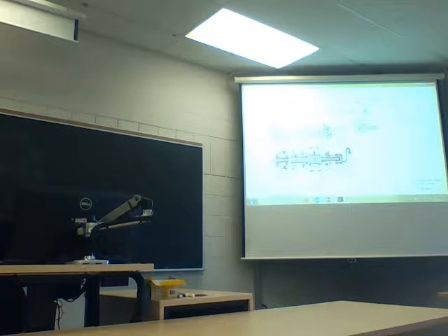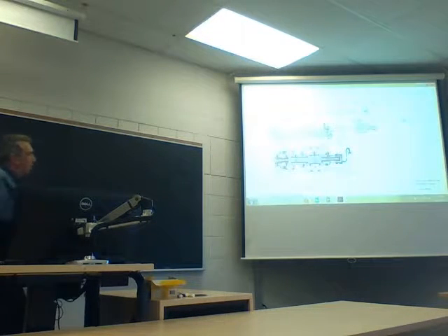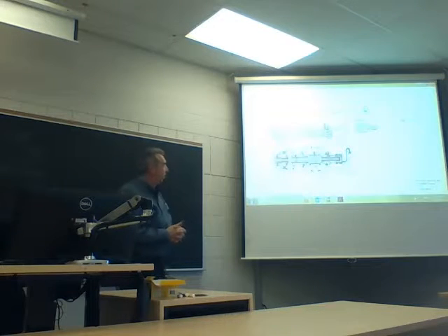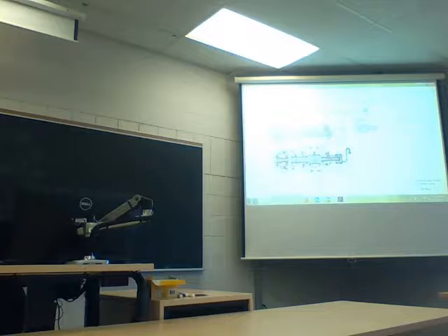It's a difficult picture to see, but if you follow the arrows through the air cooler, which is cool. Does anybody know why that's an intercooler and not an aftercooler? You notice that after the last compression cycle, it does not go after, but it's after the first and after the second, but before the third. So it's an intercooler like that.